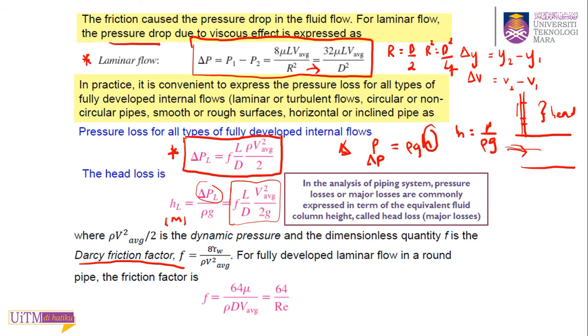Alright. So the friction factor F is important. This is the most crucial parameter, because the others you can find, or they are given in the question: the length of the pipe, the diameter of the pipe, the rho of the fluid, the velocity of the flow, and you can calculate the velocity. But this F, what is called the Darcy friction factor, we need to determine. We need to calculate that friction factor, because we use this F in this equation. This one also has F.